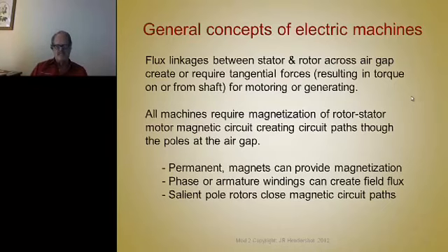So the stress is that force generated, or the torque generated, converted to a force by dividing the radius back out, and then dividing that force by the swept air gap area. That would be pi d times length, and we're going to look at that again later when we're sizing machines. But that's the air gap stress we're talking about.